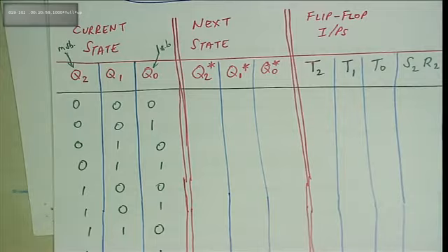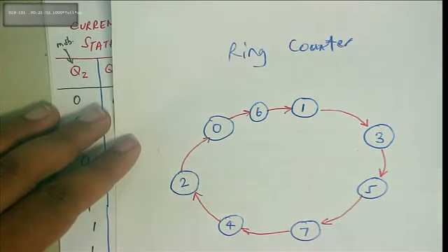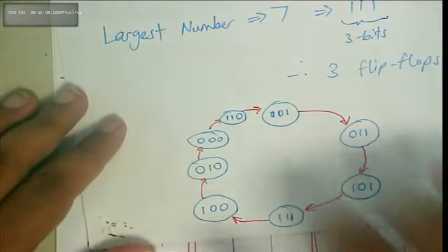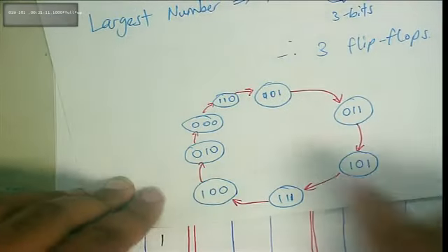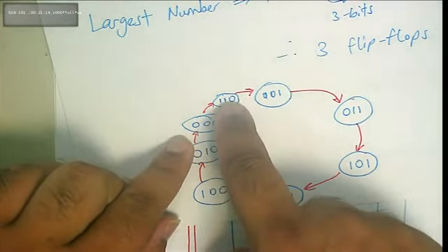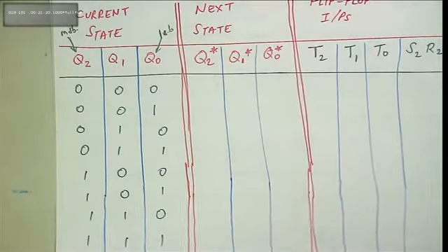We did the state diagram of the ring counter in decimal form, just from the question. But decimal does not help us because our design is in bit form, so we translate into this. So let's have a look. If it's 0, 0, 0, on the next clock trigger, what will it become? It will become 1, 1, 0. So let's follow that up.